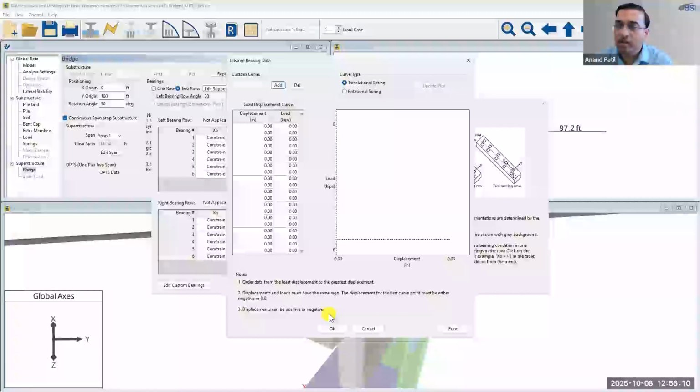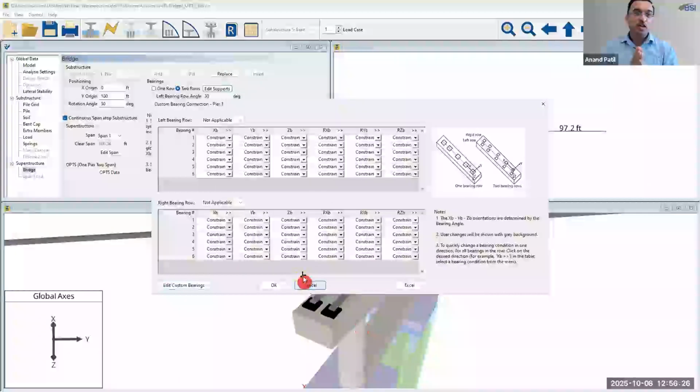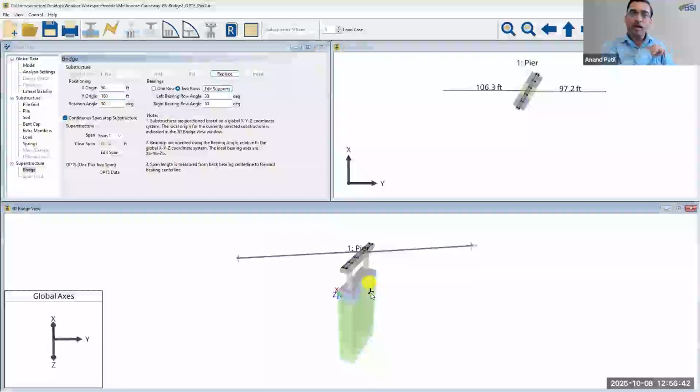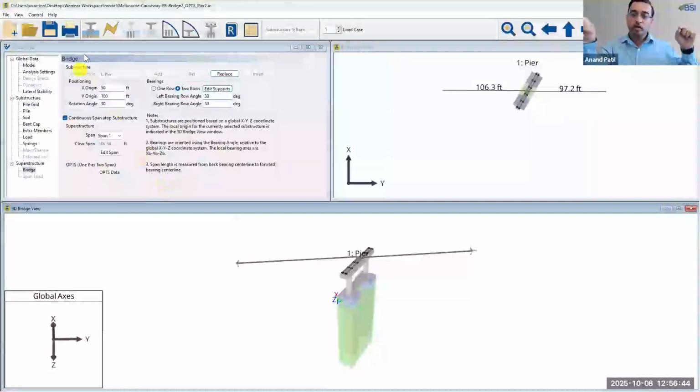How could you add curves and super elevation to bridge models where piers are not in line? Oh yeah, if it is not in line, you can have different coordinates for each of your piers. So Wilmer, if you move the middle pier out in X and Y direction, not in the line, right? If you move it out, by default the program will attach both piers together with a straight line superstructure.